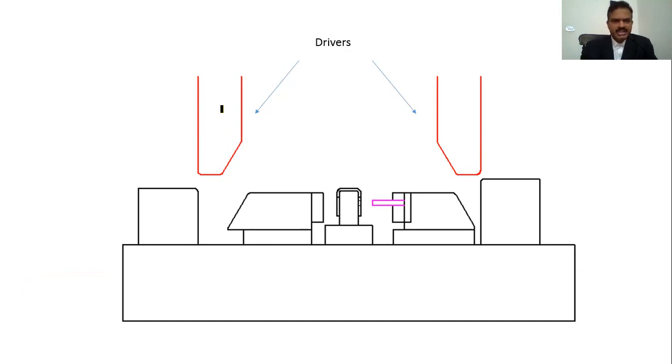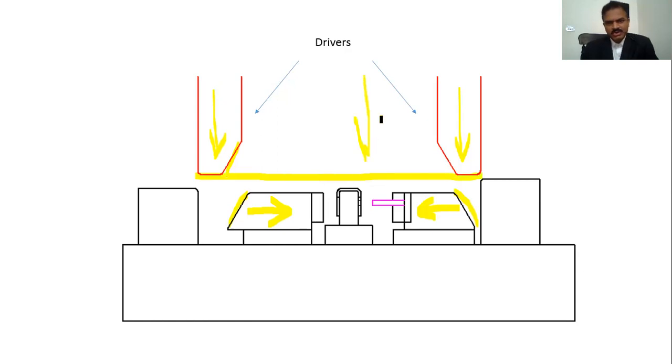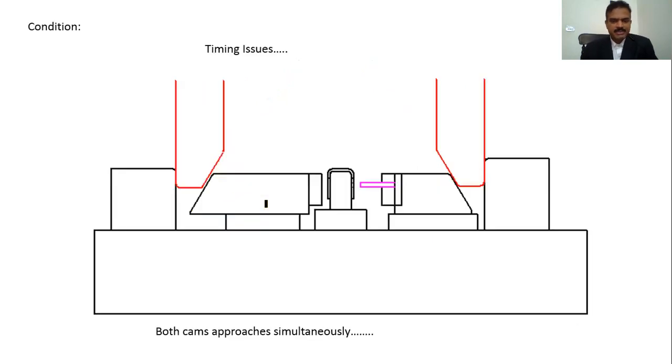Now you need a driver. See, the driver will come down, and it will push on the supplementing angle here. So the cam will move forward, and this again will come down. Again, these supplementing angles will get engaged, and it will get pushed forward, and this will support here. But observe it closely. These two are in the same line, right? When it is going to come down, it will engage both cams at the same time. It will engage simultaneously.